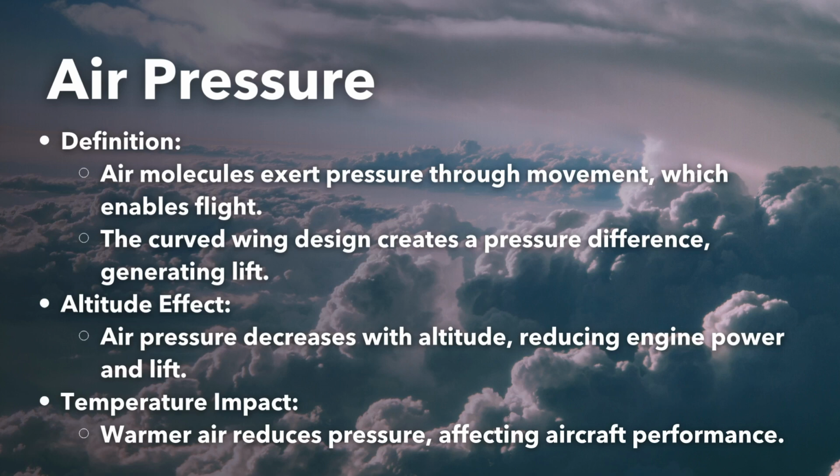Air pressure decreases with altitude, and this reduction in density impacts aircraft performance. For instance, as air pressure drops, aircraft engines produce less power and wings generate less lift, requiring pilots to adjust their operations, such as reducing cargo weight. Air pressure also varies with temperature, as warmer air causes molecules to move faster and spread out, thus reducing pressure. This relationship between temperature and pressure is key for predicting aircraft performance on any given day.